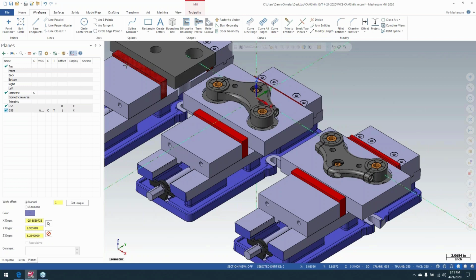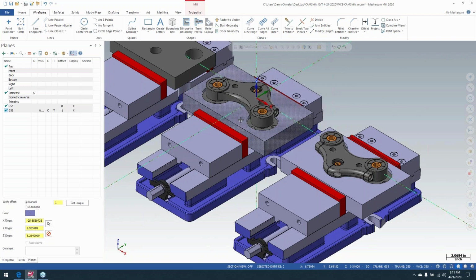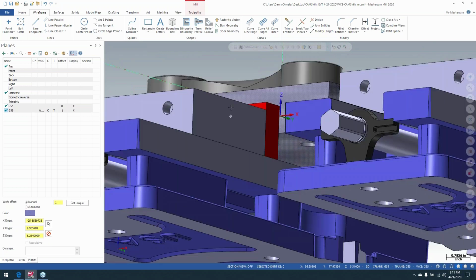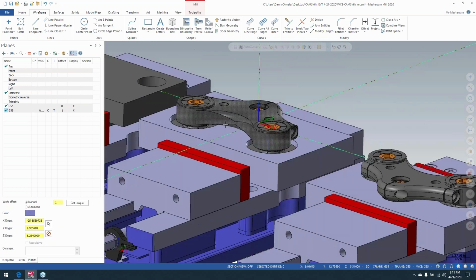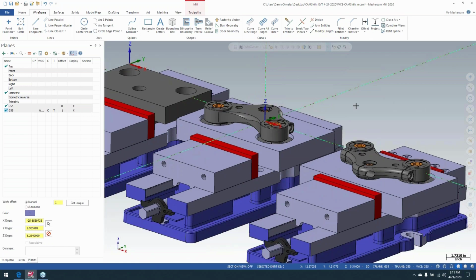So we're starting with some raw material. Then we're going to machine, once these holes are here, we're going to flip it over, put them in location, clamp them down with the expansion, and then mill the outside of them. Once that's done, then we still have to machine the step on the bottom and the other fillets. We'd flip the part around and go ahead and machine that.